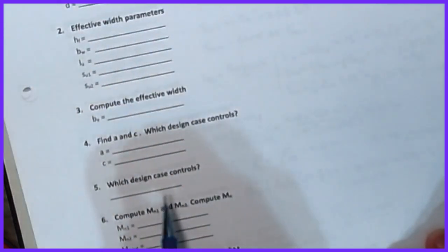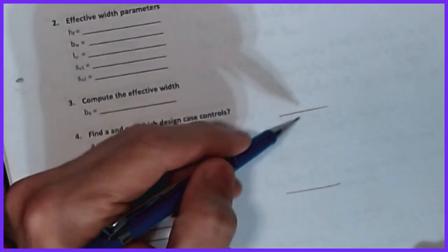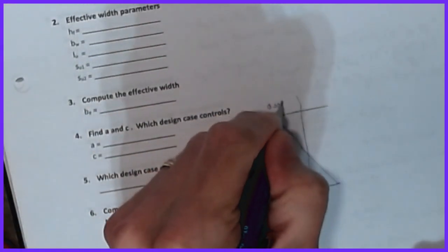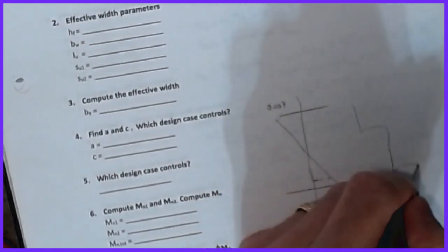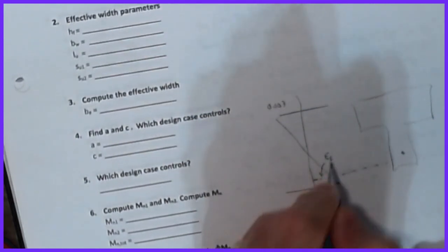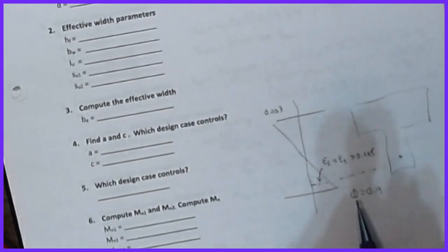We didn't show that check in this exercise, but remember that if my strain diagram looks something like this, where I'm at 0.003, and I realize I drew this backwards, but you get the idea, somewhere down here, if my T-beam looks like that, there's my As, and this is my epsilon s. In this case, if it's one layer of steel, it's epsilon t, and that needs to be greater than 0.005 in order to get a phi equal to 0.9. So that's the other check that you have to do.